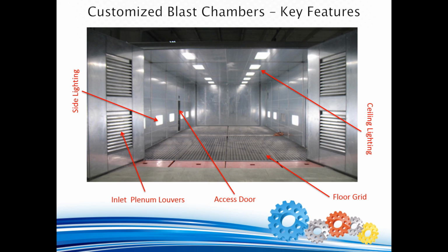In the case of PanBlast's Waffle pneumatic recovery system, using the 2-in-1 full-floor concentrator system for both blast chamber ventilation and media recovery, we have a downdraft airflow instead of the standard cross-draft airflow. In this situation, the inlet air louvers are spread out evenly across the top of the blast chamber ceiling instead of being located at the front or entry of the blast chamber.